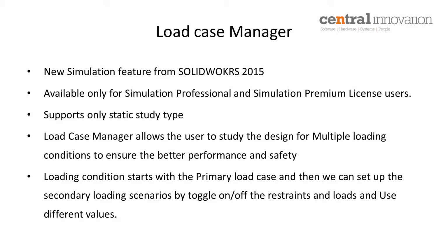So if you have a standard or SolidWorks Premium, you can't use Load Case Manager. And the next thing is this Load Case Manager supports only linear static analysis. So if you want to perform a dynamic analysis, if you want to perform a frequency analysis, you can't use a Load Case Manager. Okay, it's limited.